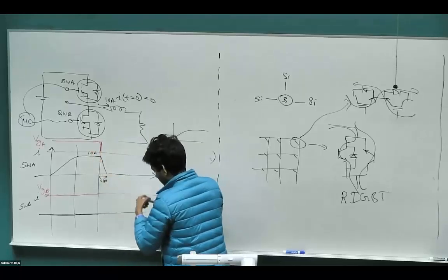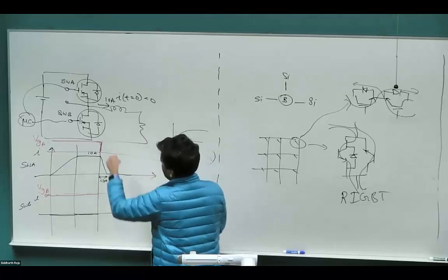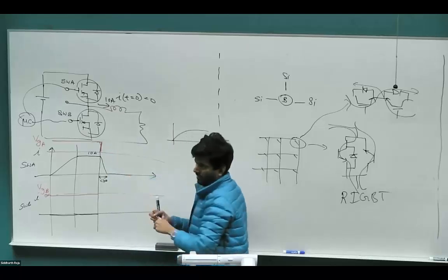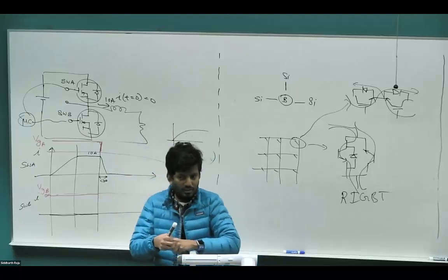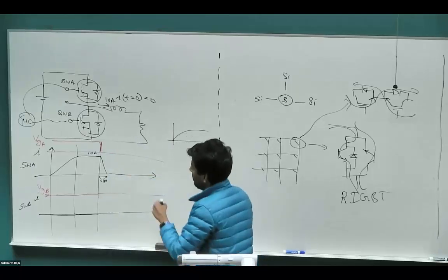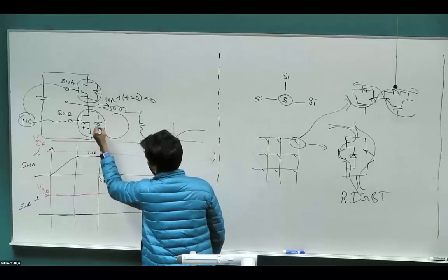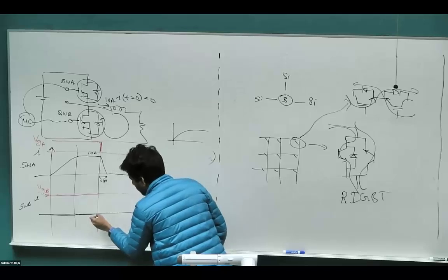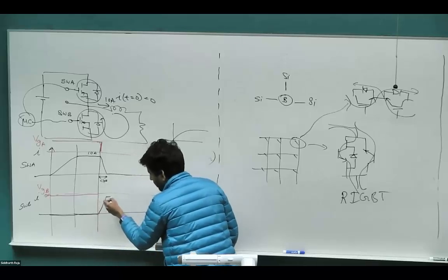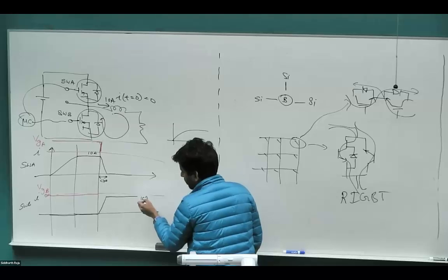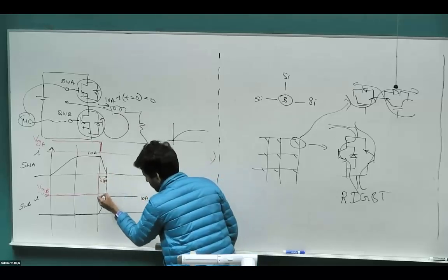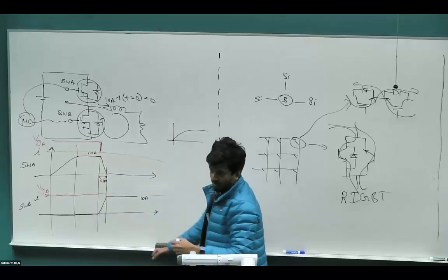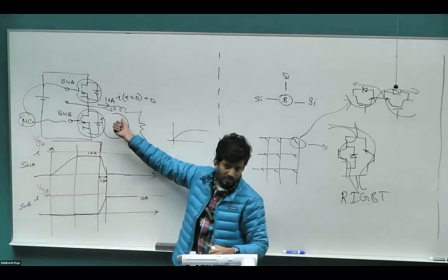So during that time, the current starts to fall down. But the sum of the current coming from here and the current coming from here must be equal to whatever the inductor current is. The inductor current cannot suddenly disappear. So what does the current do? A portion of it splits and goes into the body diode of the bottom switch. It starts to build up and get to 10 ampere during this time period, so that if you take the sum of this current plus this current, that would always be equal to 10 ampere flowing through the inductor.